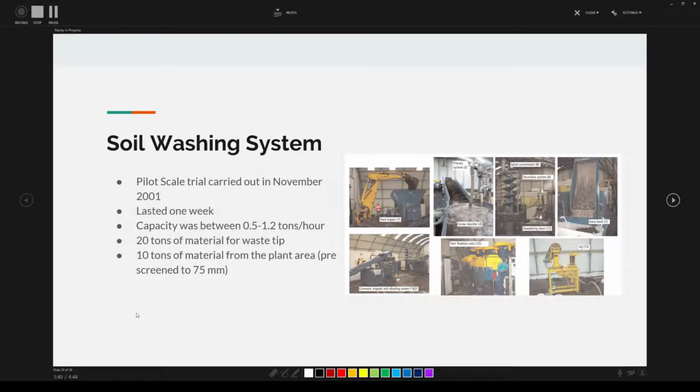The same picture also shows the secondary cyclone, which is a 3-inch stub cyclone or hydrocyclone, overflow to carrier, underflow to flotation conditioner, and this removes the abraded contaminated material released from attrition scrubbing the sand-sized material. It also shows a dewatering sieve. So this reduces the water content of the clean sand slurry to about 75% solids by weight.